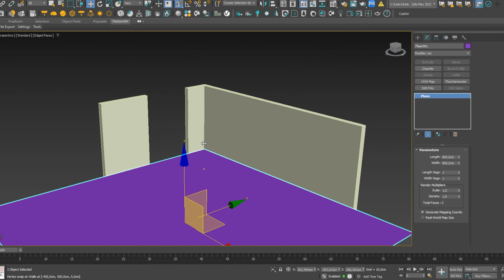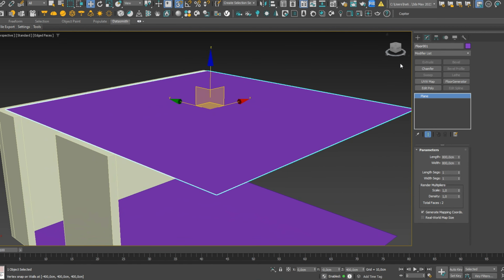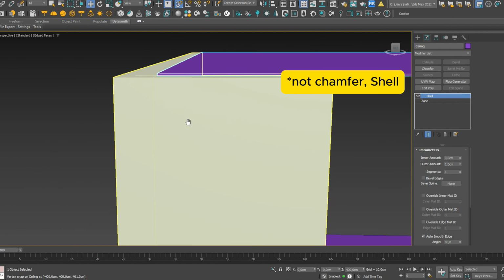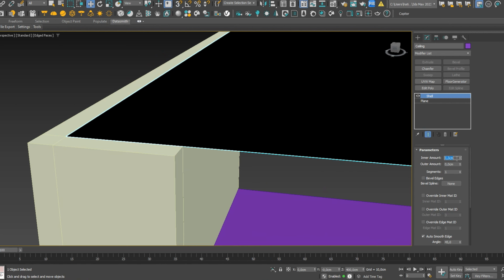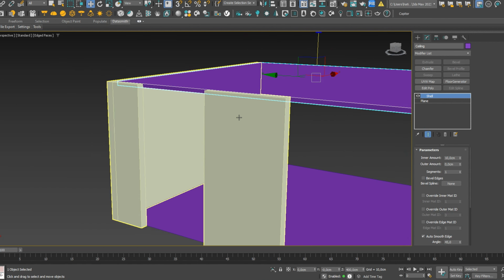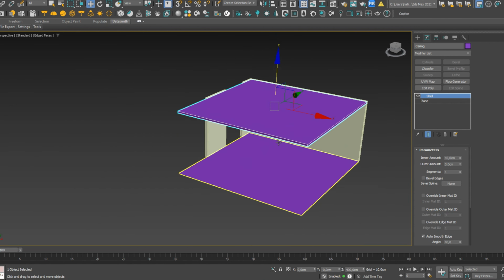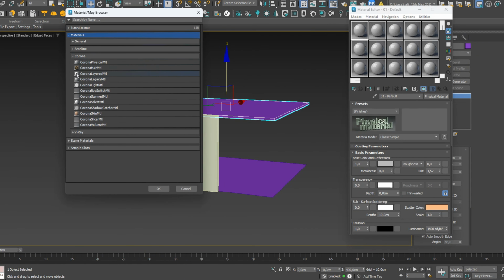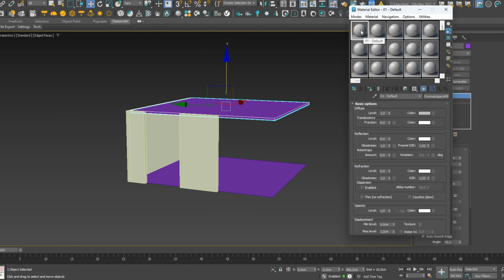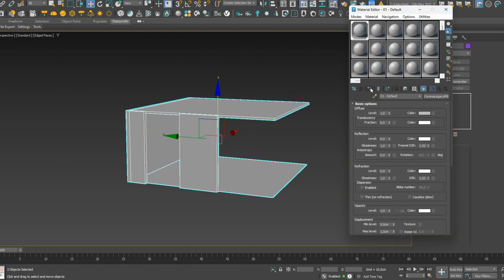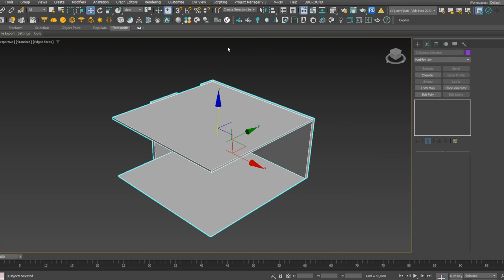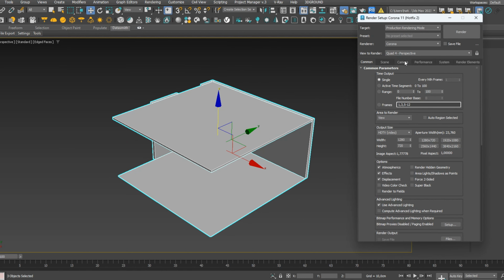By copying the floor, I created the ceiling above. I applied the chamfer command to it, but because auto removal was selected, I reset it and entered value of 1 with the inner removal tool. I got the ceiling the way I wanted. Then I created a basic color for the metal parts using the Corona material and assigned it to base color.